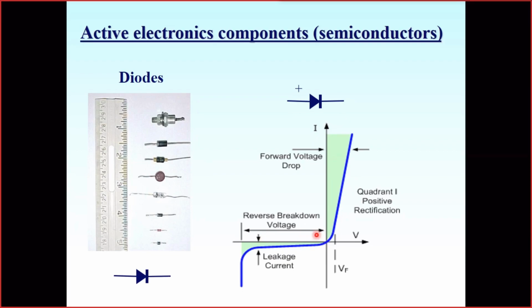We may decrease the capacity of the PN junction if we use not just a PN junction of two semiconductors, but a junction between a P semiconductor and a metal. Such diodes have higher leakage current than the usual ones, but they have the lowest junction capacity possible. Such diodes are called Schottky diodes. They are used exactly for high frequency applications.